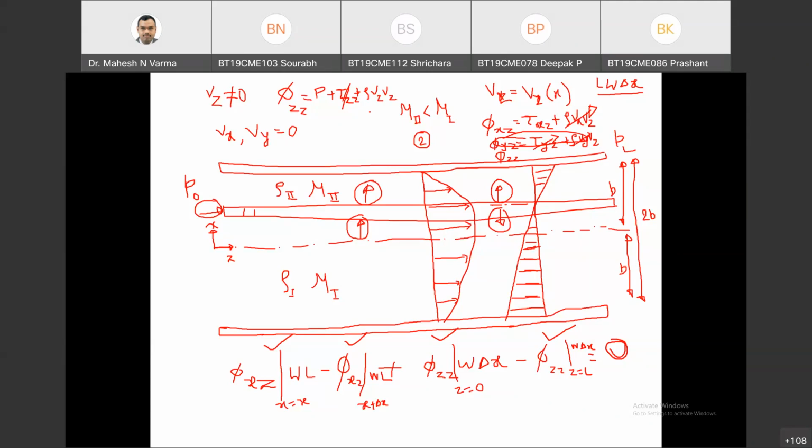Yes, sir. So you are correlating density with velocity. Actually, you have written something in the chat box. Yes, sir, when we were discussing the velocity profile. But that is not velocity. The magnitude of velocity is governed by the resistance to flow, which is viscosity, not density.